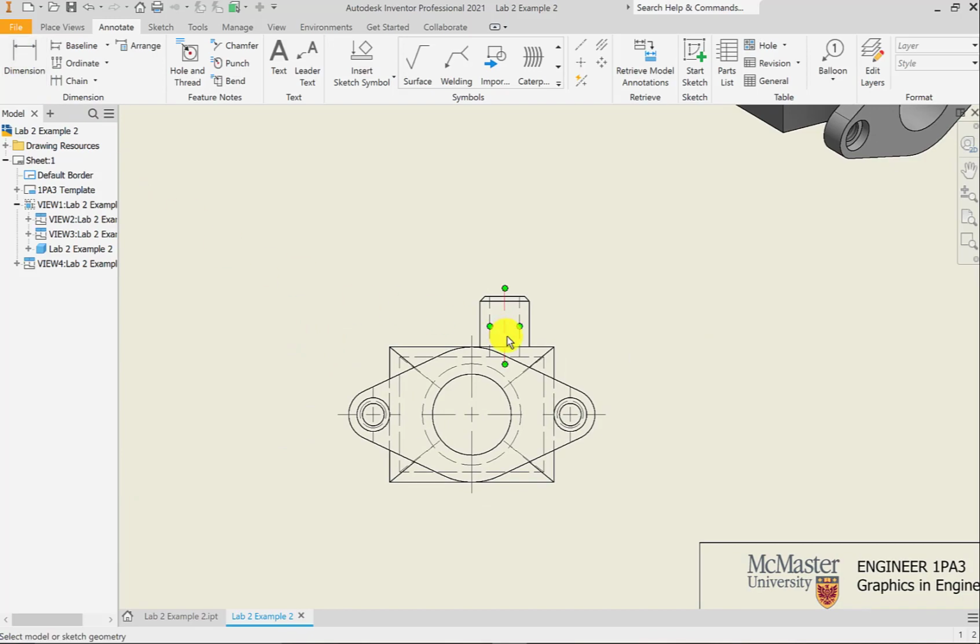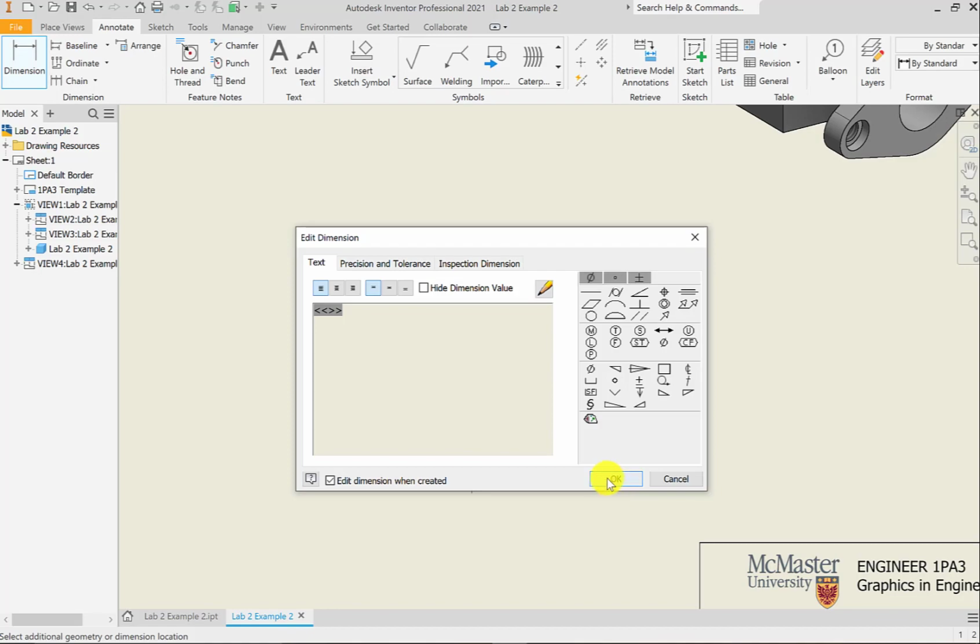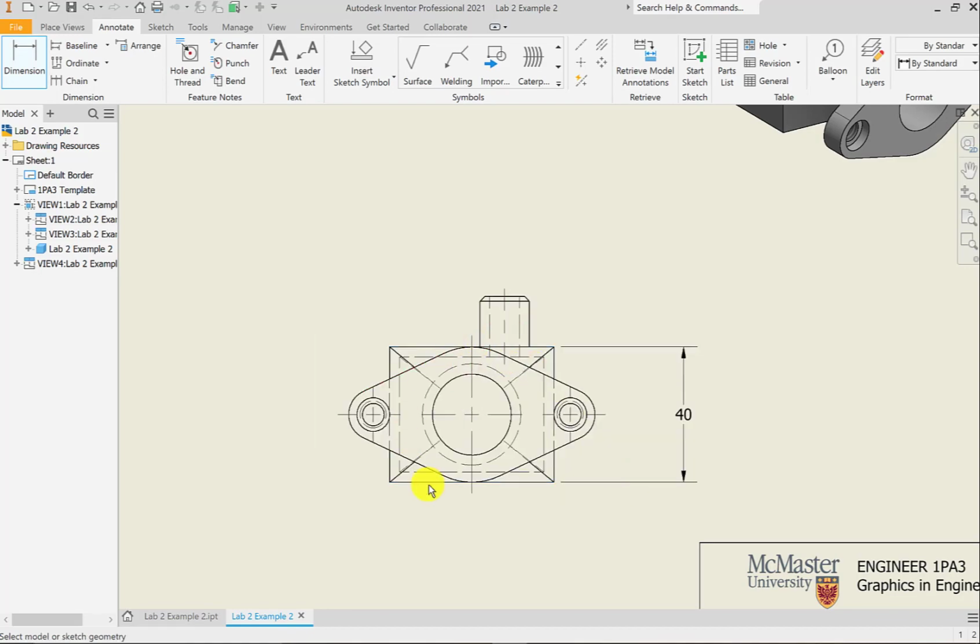Specifically, we'll indicate the overall height of the rectangular prism, which we can also see in this view is equivalent to the height of the outer extent of the flange. We can also indicate the height from the base of our holes. So this shows that the central hole is aligned horizontally with the two holes on either side because the center marks are aligned and they're all halfway up the part. We can also dimension the position of this center hole from the back edge of our part. That happens to be 25 millimeters.